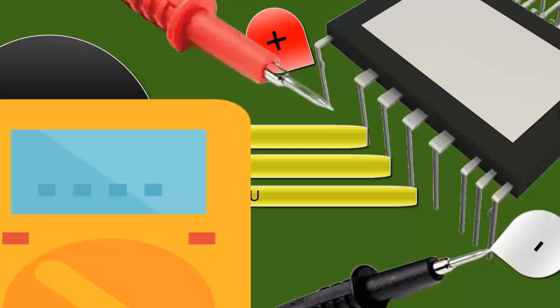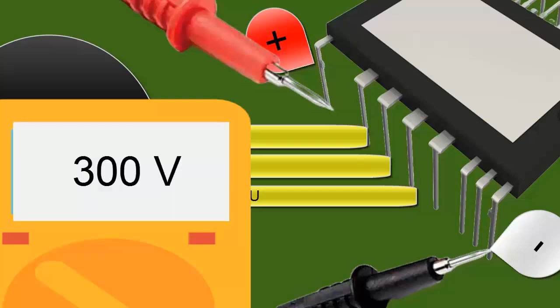E. The power supply value will depend on your electronic board's power supply, expecting values around 150 volts for a 110 volt supply and approximately 300 volts for a 220 volt supply. F. If no power appears, the issue with the external electronic board lies in the power supply, and not directly in the IPM electronic circuit.